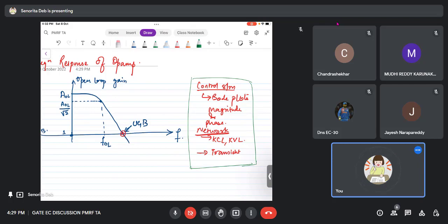Okay. So op-amp is a direct coupled amplifier, therefore the voltage gain will remain constant at low frequencies, okay? But it will decrease at high frequencies due to capacitance effects, because inside the op-amp it is all MOSFETs or BJTs. So capacitances will come, and this is the effect that you are seeing right now, a decrease in the gain with respect to the frequency.